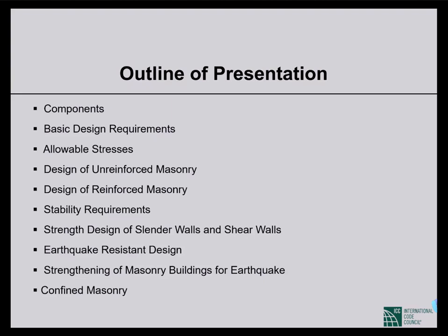For basic design requirements, we have discussed the effective height, effective length, effective thickness, and slenderness ratio. For allowable stresses, since we adopt working stress design, we calculate allowable stresses for axial compressive stress, flexural stress, tensile stress, and shear stress. We have all those formulas for allowable stresses.